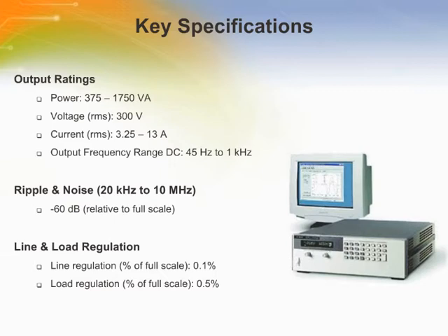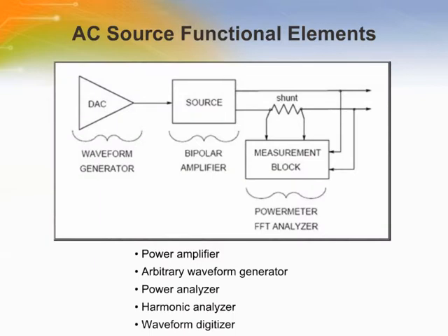The Agilent 6811B provides a complete AC and DC power and measurement solution with extensive features to protect valuable DUTs. The AC source combines three instruments in one unit, as shown in the following figure. The function generator provides waveforms with programmable amplitude, frequency and shape. The power amplifier amplifies the function generator signal to produce the AC power for your application. The measurement functions range from a simple readback of RMS voltage and current to sophisticated capabilities such as waveform analysis.